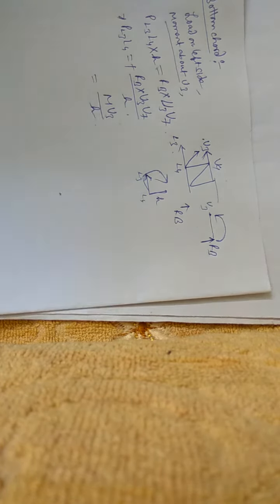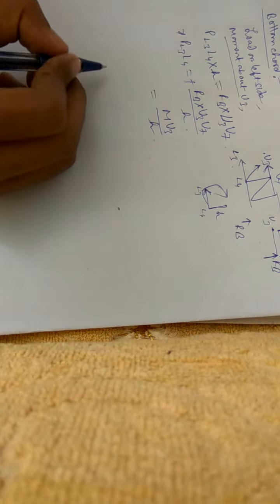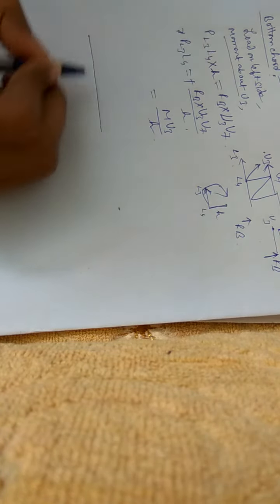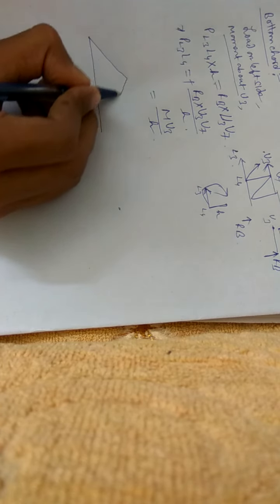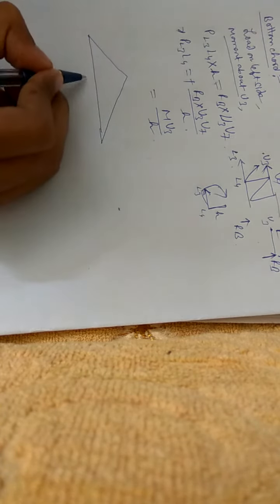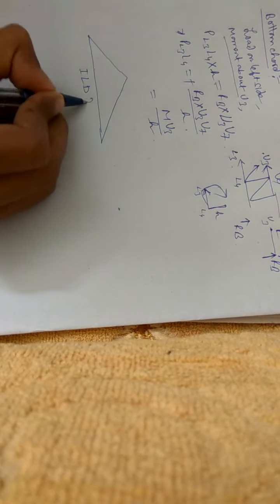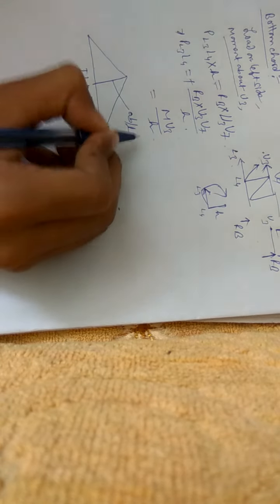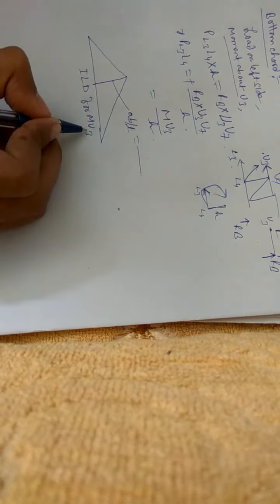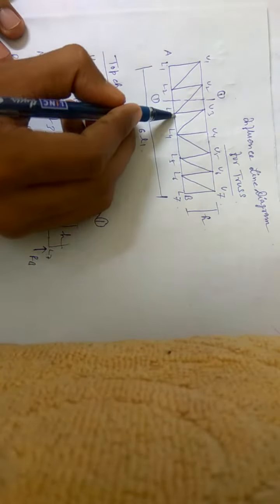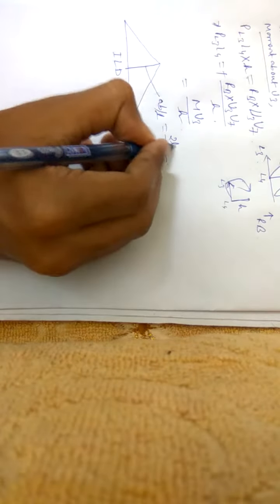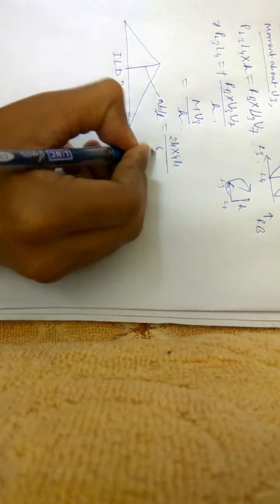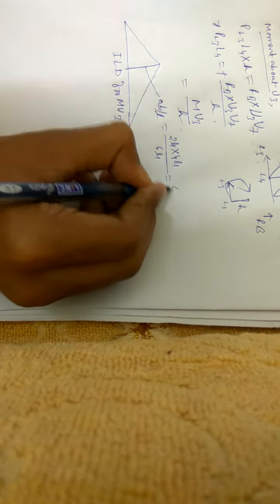And you know how to draw the ILD for MU3. So now I will directly draw. All these are ILD for moments for MU3. So this will be AB by L. So what is U3? Okay, let's see U3. This one, L3, this is 2L1, 4L1 by 6L1. Same. 2L1 into 4L1 by 6L1. It will be 4 by 3 L1.